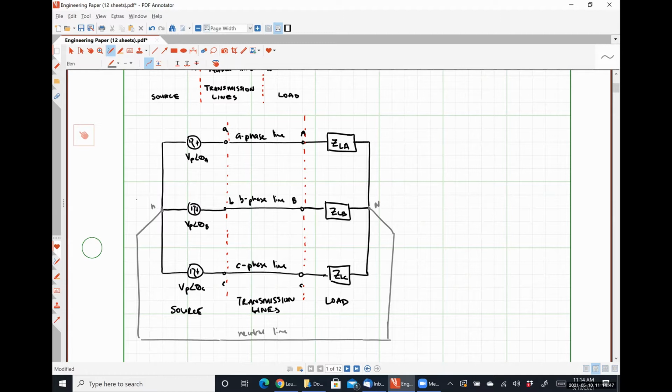There is another advantage that has to do with electrical machinery. And when we get into the power analysis, it will become evident. But a 3-phase voltage system like our source here is capable of creating a constant torque in a rotating electric machine. So what that means is that if the torque is constant, effectively the motor doesn't vibrate.